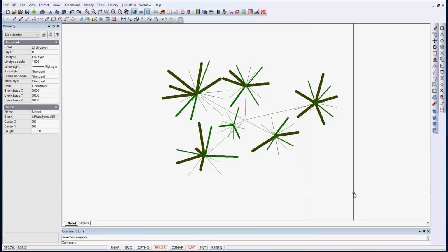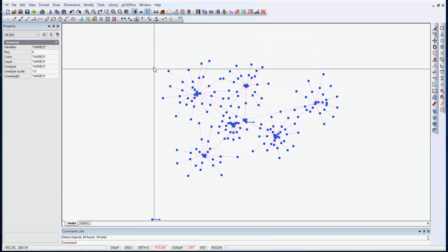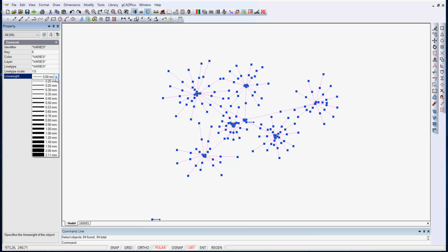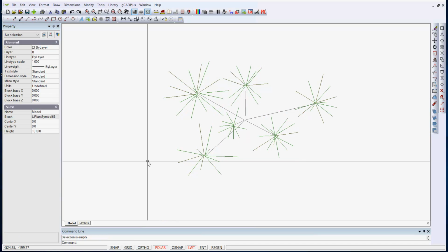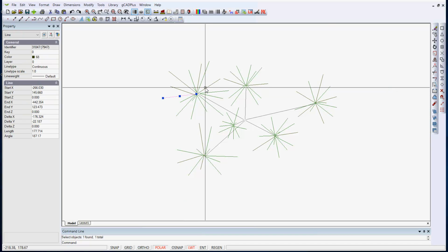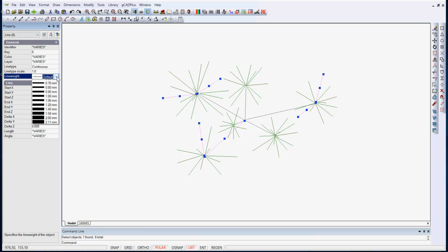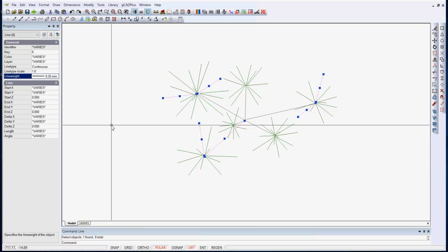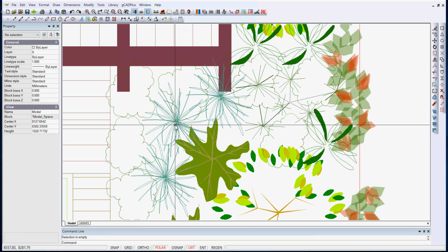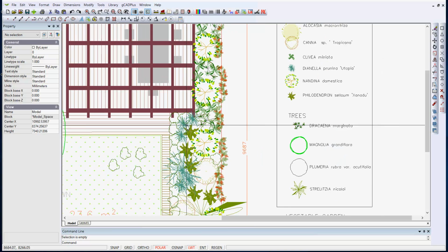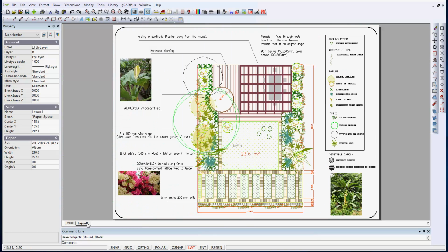One can see what the designer is trying to do there to get some varying weight, but I think I'd be inclined to bring these back again to the default one, and if you wanted some thickness within here, why not be not quite so bold? So we'll make some of these a line weight of say 0.35 and then close the block editor, and I think that satisfies me. It's not a big blob of colour.